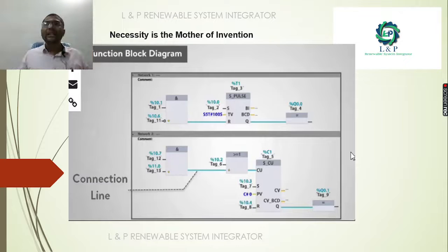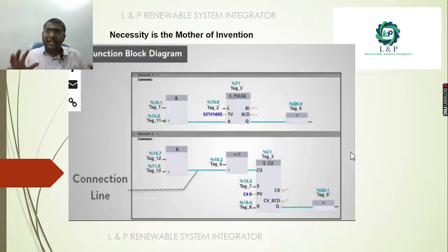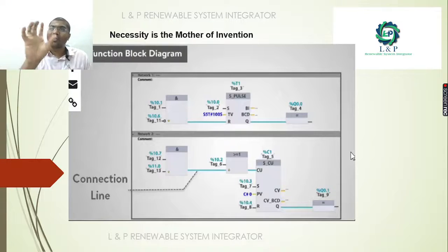They have multiple inputs and multiple outputs. If we use ladder logic with the old methodology, the program will be very big, very complex, and consume more memory. So to reduce it, they thought: I need a single block diagram for all sorts of AHUs, and the only thing I need to change is the address and the tag name. So there came the function block diagram.